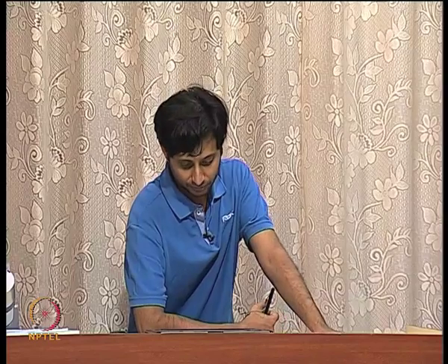If the capacitor is an open circuit, whatever you apply at the input is never going to reach the output. So, the output should be equal to 0 volts at omega equal to 0. Your expression also says the same thing. At infinitely large frequencies, the inductor is an open circuit, which means once again that whatever you apply at the input is never going to reach the output. So, the output should be 0 volts.